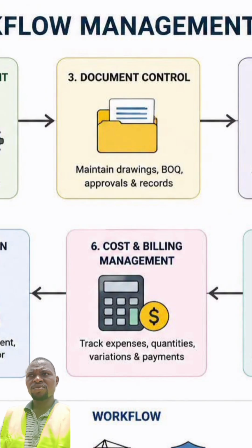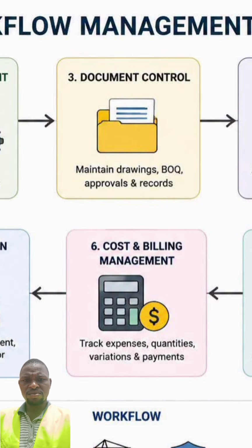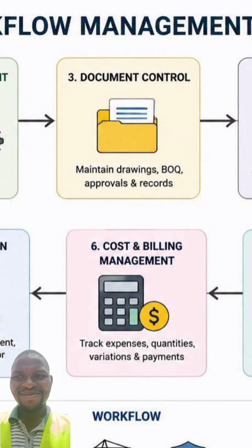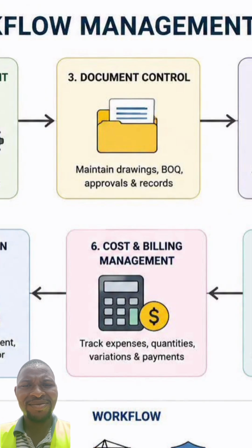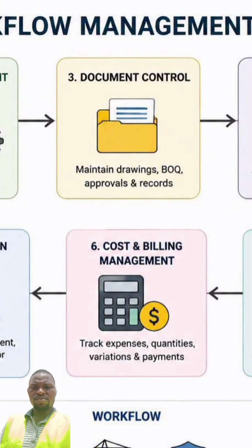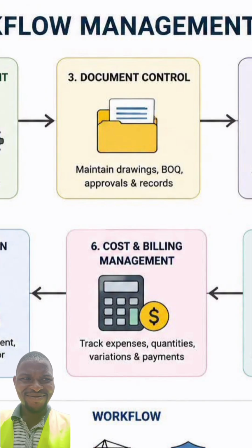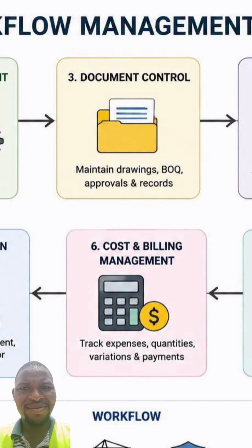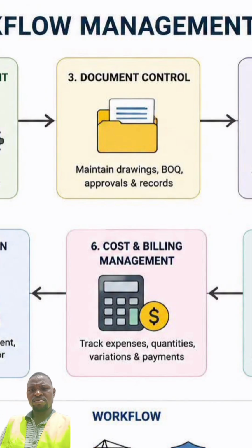So I think the main drawings, right? You have your architectural drawing, your structural drawing, your electrical drawing, and your mechanical drawing. So these are the vital drawings that you actually need during your construction. Then from these drawings, that is where you're going to do your BOQ or BEME, that is your Bill of Engineering Measurement and Evaluation. And this bill actually helps you to get figures for all these estimates.